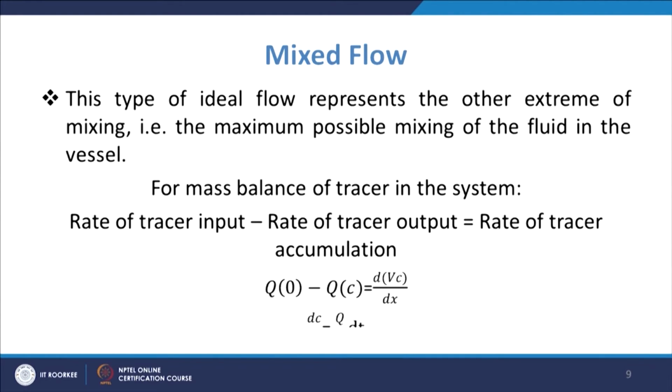The mixed flow is the type of ideal flow that represents the other extreme of mixing, that is, the maximum possible mixing of the fluid inside the vessel. In the plug flow, the elements maintain their identity, whereas in the mixed flow it is assumed that once the tracer has gone inside the vessel, it is completely mixed inside.